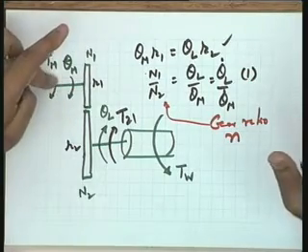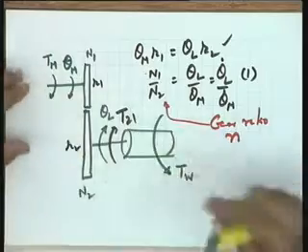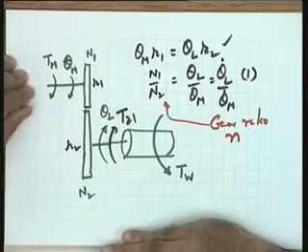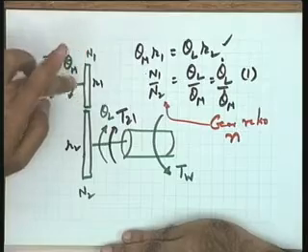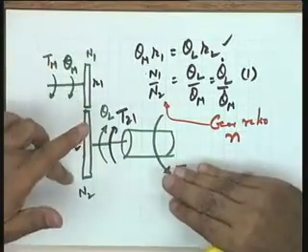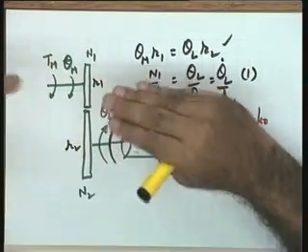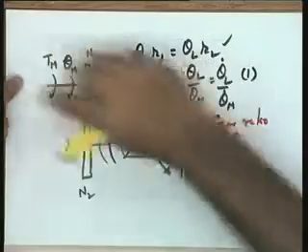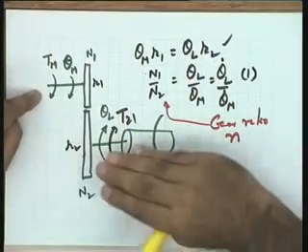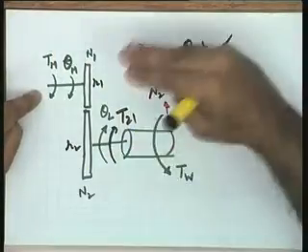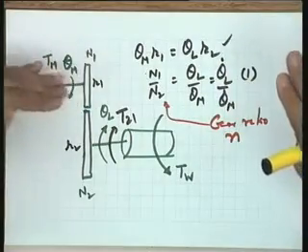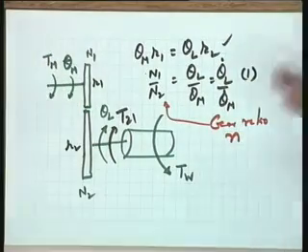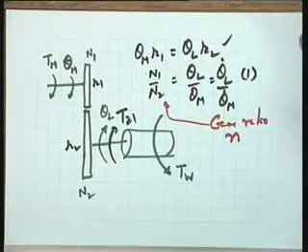How about the gear 1? Please see that if I remove gear 2, the total load torque on gear 1 will be less compared to the situation when gear 2 is present. It means as far as the motor shaft is concerned, the gear 2 and the load is loading the motor shaft. Just look at the motor shaft only. The motor shaft is being loaded. You can see the two situations. Without the gear 2 and with the gear 2, the situation on the motor shaft becomes different.